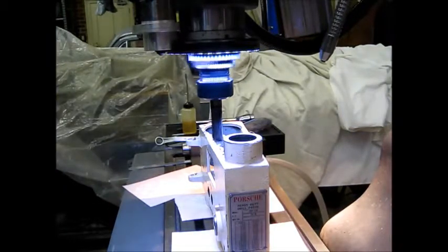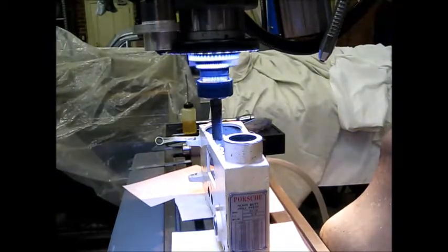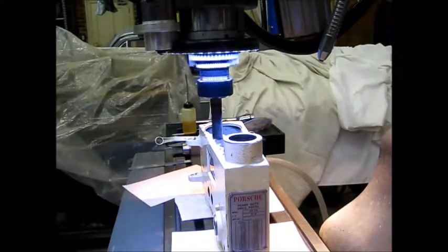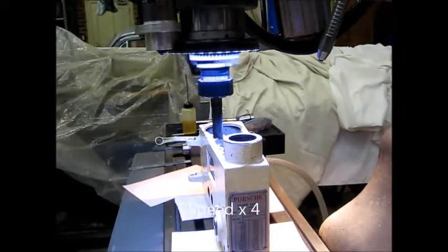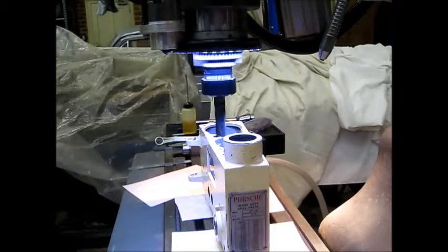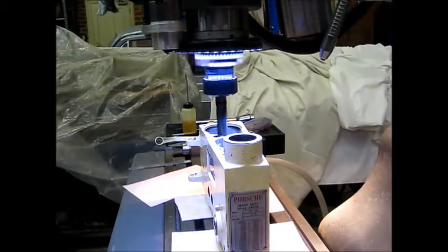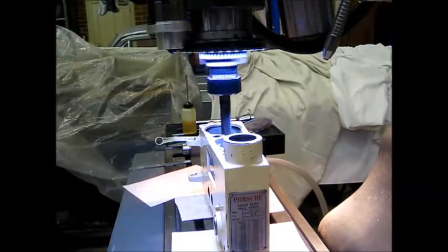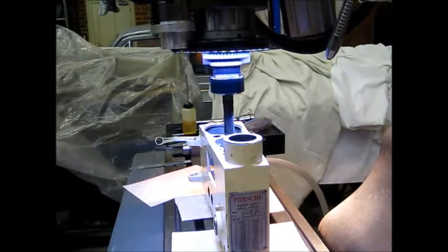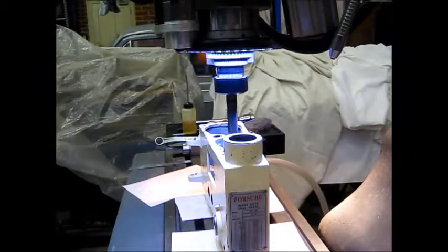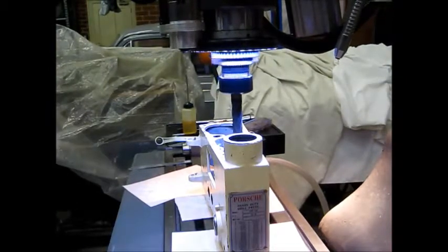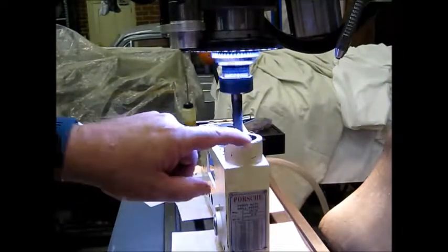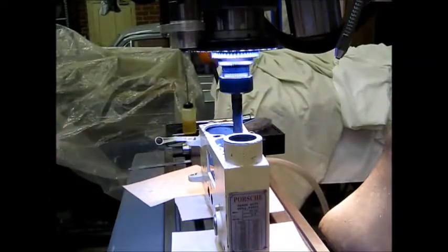I'm going to speed it up a little bit because it's not cutting anymore there now because of the eccentricity of it. I'm using the feed rate override, and we'll step it up. I'm up to 150mm per minute. I'm keeping going because there's nothing cutting. And now it's finished on the other side there. The first G code has travelled 180 degrees around the part.